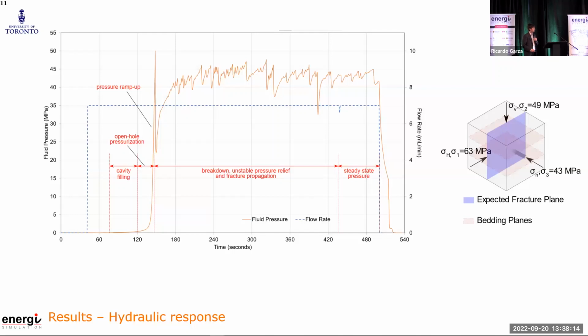So theory is telling us, when you study, that when you inject fluid in a medium under polyaxial, so sigma 1, sigma 2, sigma 3 stress conditions, you basically create a fracture that opens against sigma 3. So the minimum principal stress opens. In this case, what we expect is a vertical fracture that opens against sigma 3.